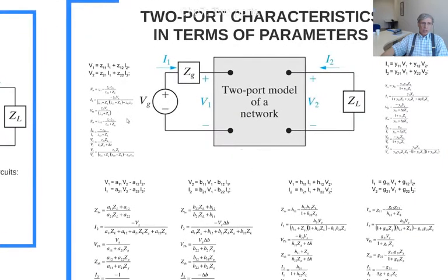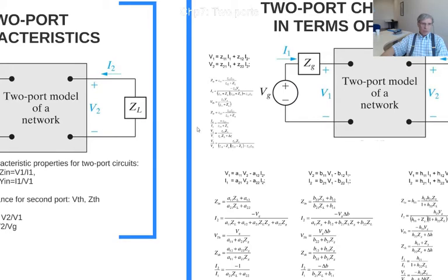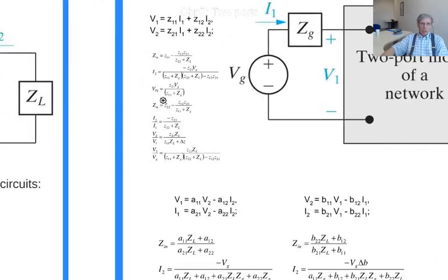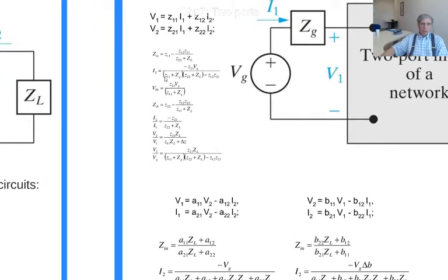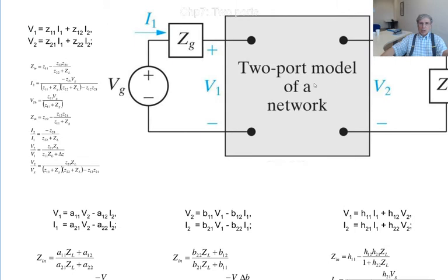So it is shown here. If you've got Z parameters, the 6 characteristics that we mentioned here can be calculated by using the Z parameters as seen here. Once you know the Z parameters of this two-port circuit, you can directly write the 6 characteristics. You could use that formula.